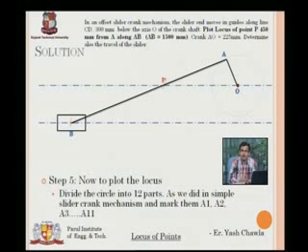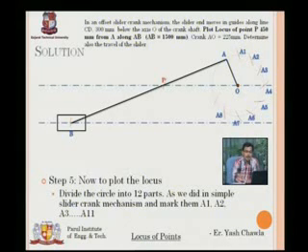So again, I'll take my protractor, keep the center at O, the base AO, and mark A1. I have not shown the steps because we did it already. Then I'll take the distance A1, keep my point at A1 and cut an arc at A2, and that will go on till A11. So these are different points of my crank at different times.